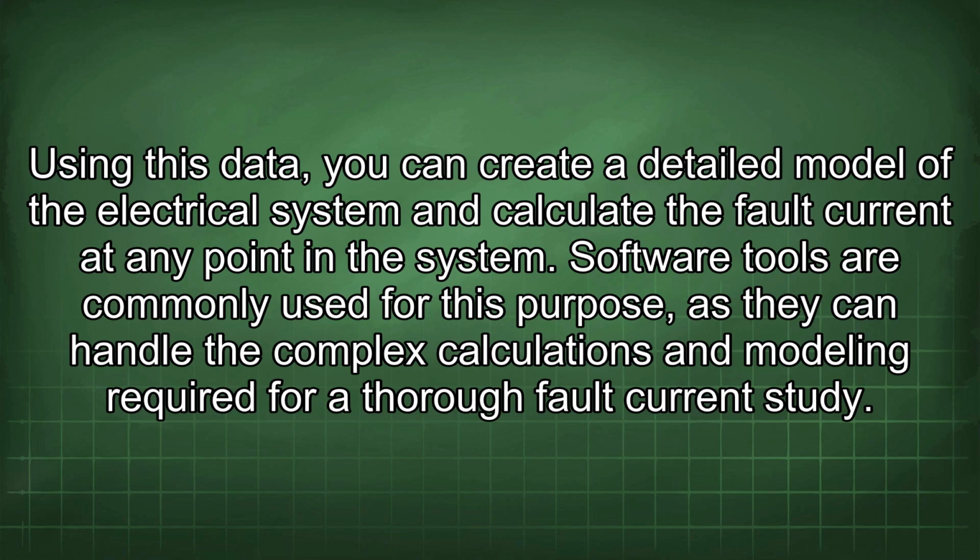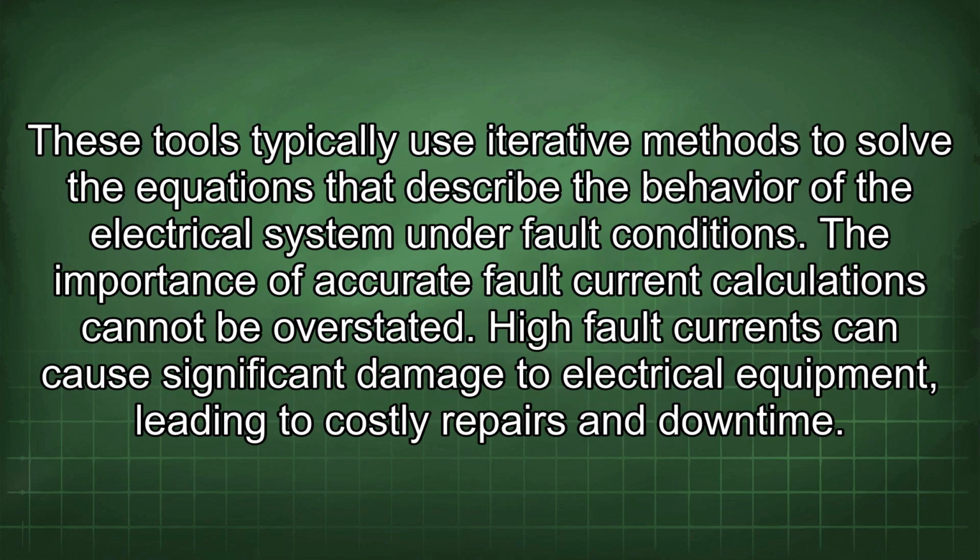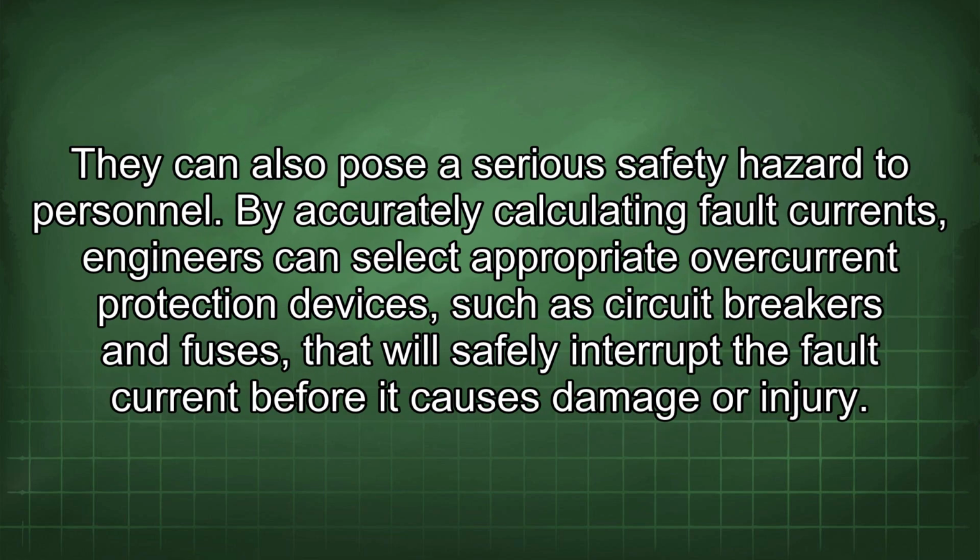Software tools are commonly used for this purpose, as they can handle the complex calculations and modeling required for a thorough fault current study. These tools typically use iterative methods to solve the equations that describe the behavior of the electrical system under fault conditions. The importance of accurate fault current calculations cannot be overstated. High fault currents can cause significant damage to electrical equipment, leading to costly repairs and downtime. They can also pose a serious safety hazard to personnel.